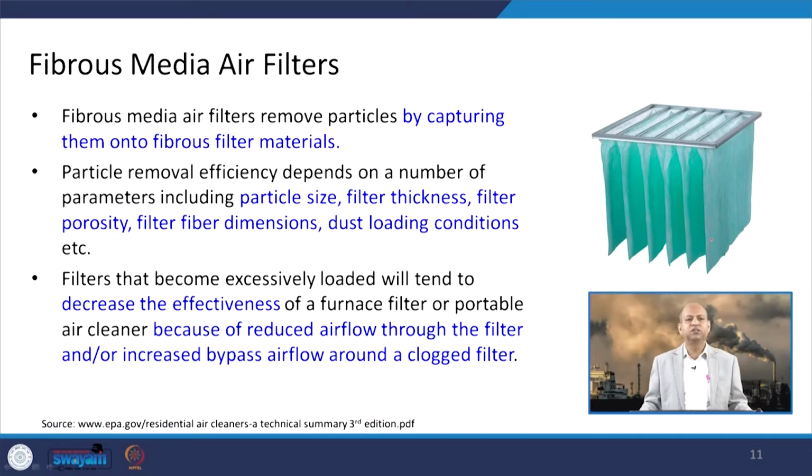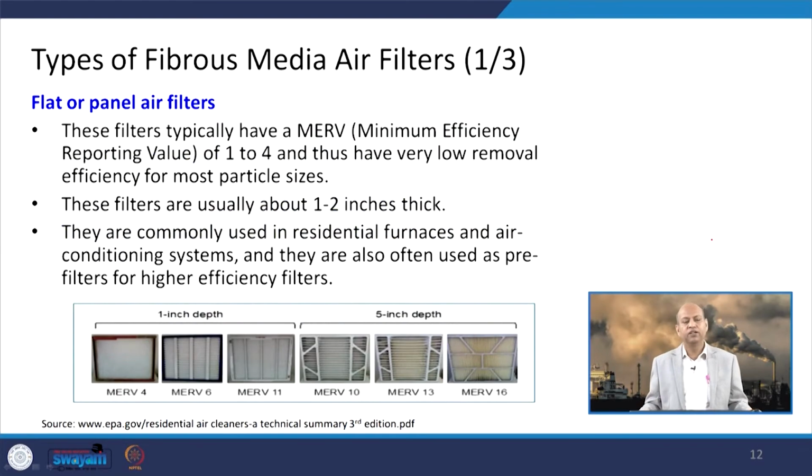And these filters that become excessively loaded will tend to decrease the efficiency or effectiveness of the filters, basically when porosity is less. Because of reduced airflow through the filters and increased bypass airflow around a clogged filter, they can rather pollute the indoor environment instead of cleaning it. So, these are things we have to keep in mind to do better maintenance, or we should frequently do something to remove those clogging situations.